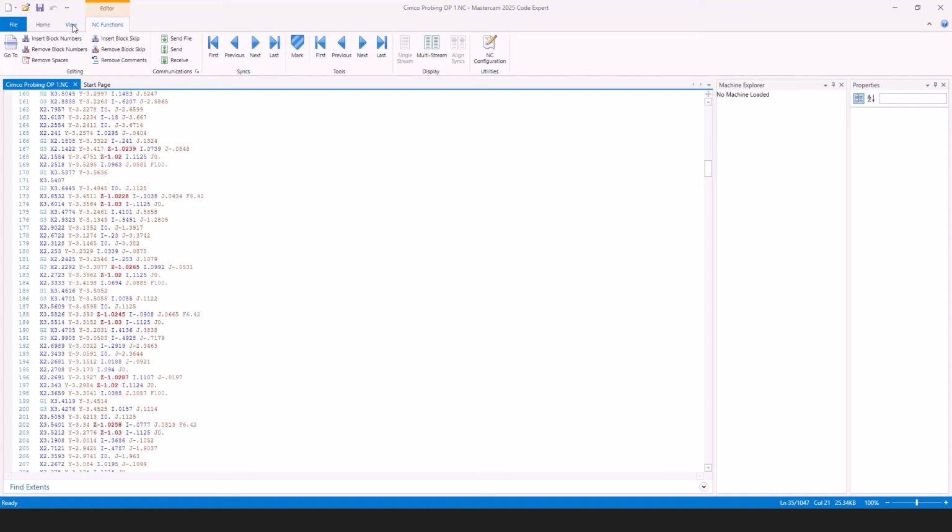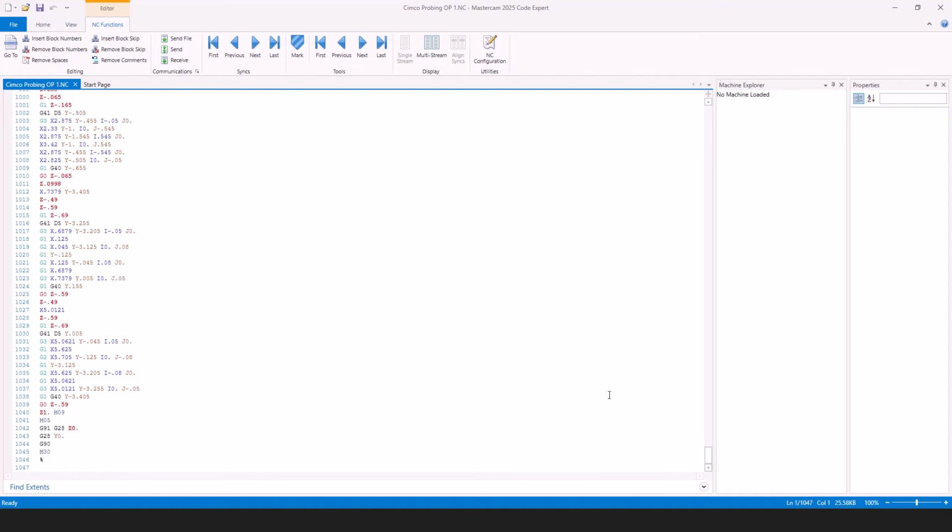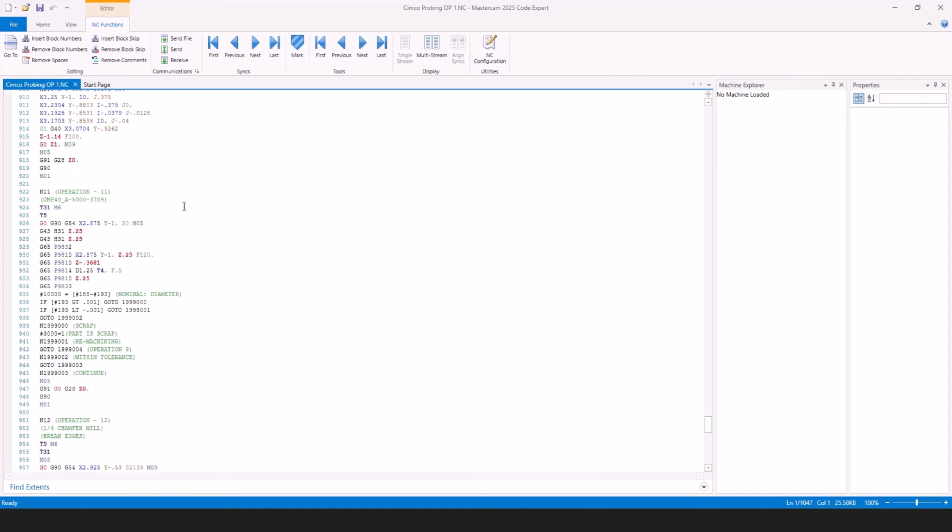Once we get into the actual machining cycles, I'm going to go ahead and skip and look for an if. We're able to get it to come out, and we're already doing our probing cycles, and then we have our if-then logic statements. They're going to correct the machine if that part's oversized.